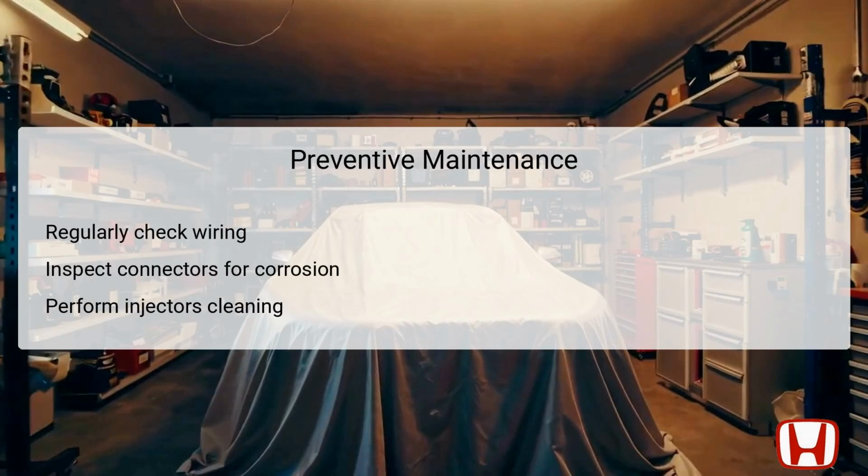Preventive maintenance plays a vital role in ensuring the longevity of the injector system and overall engine performance. Regularly checking wiring can catch issues before they escalate into serious problems. Inspect connectors for signs of corrosion or damage, as this can hinder proper electrical flow and lead to malfunctioning components.